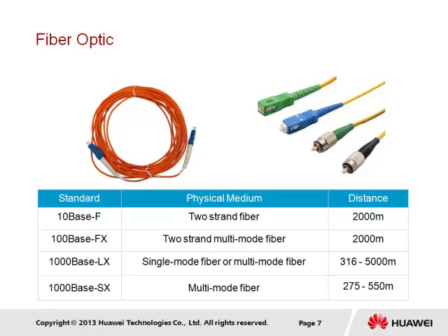Another reason for the growing popularity of fiber optic medium is its capability to support gigabit Ethernet transmission rates of 10 or even as much as 100 gigabits per second, with the potential for even greater rates. Two modes are used to support optical transmissions: single mode and multi-mode. A single mode fiber will only support a single optical signal, for which transmission distances can reach tens of kilometers. Multi-mode involves transmission of multiple optical signals over the optical fiber and can generally be understood to have a much shorter transmission range. A number of different connector types also exist. However, common standard types include the ST, SC, and LC connector types.